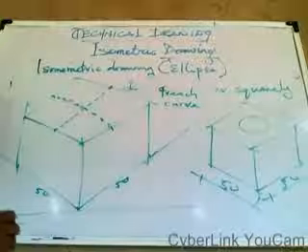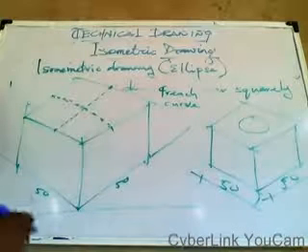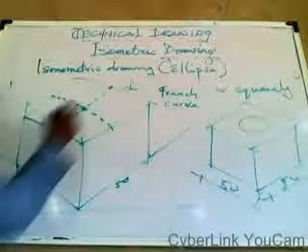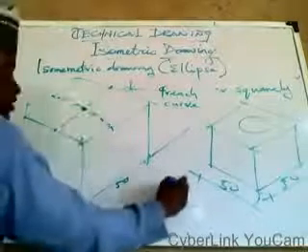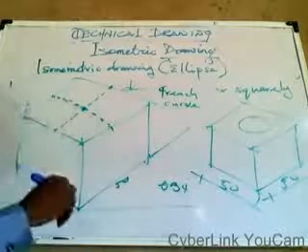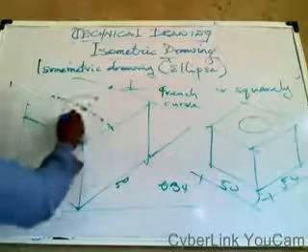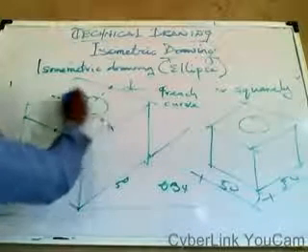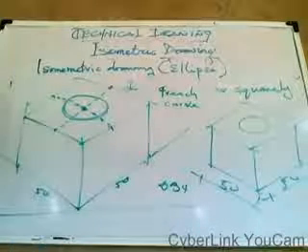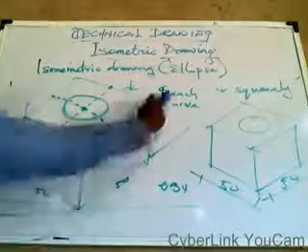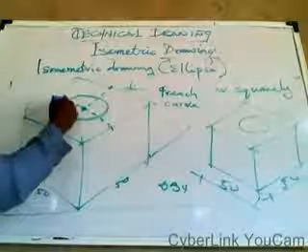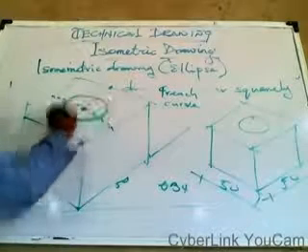So at times you will be given the diameter of the ellipse you want to draw. So this is the center of that particular dot. From your French curve, now look for the diameter. Let's say you are given 34. Diameter is 34, so look for the 34 on that French curve. Then you produce something like this. So the meaning of this is that when you want to draw an ellipse in isometric, a French curve is required. You must have a French curve in order to get the shape of the ellipse.